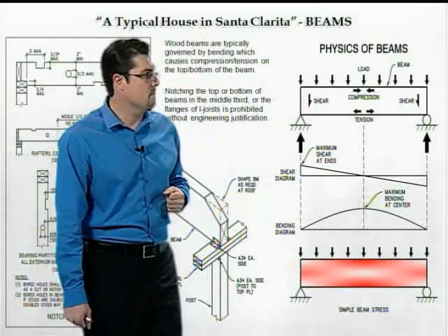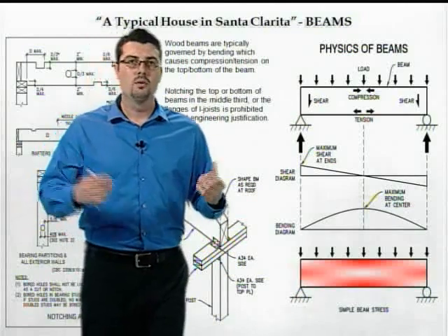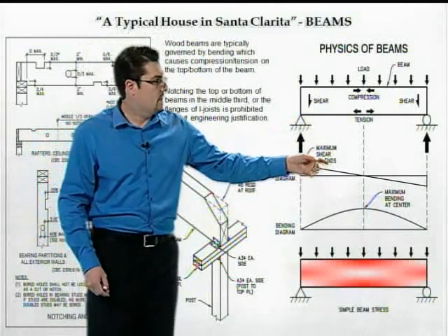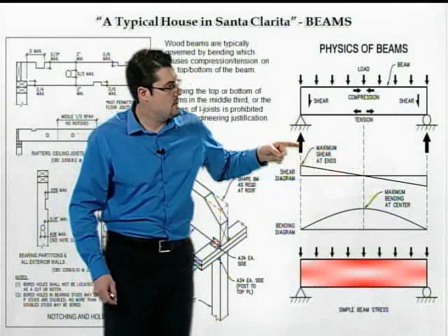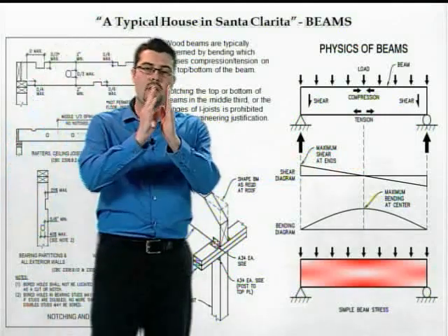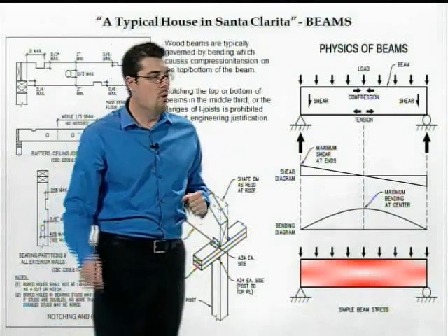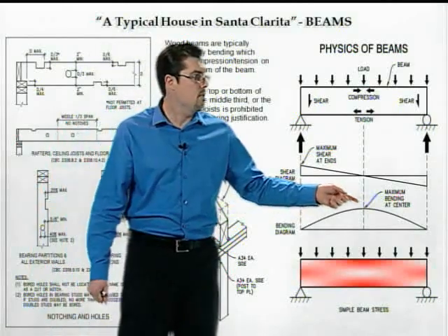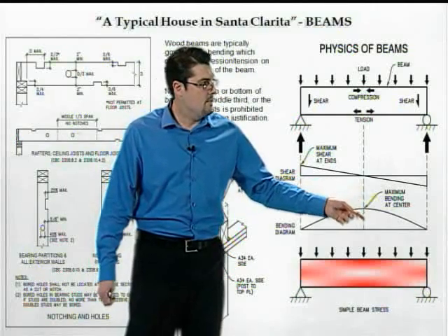Now, typically in a beam, when you load a beam from the top, it generates forces inside the beam. We call these forces shear and bending. As the load bears on the beam, the shear forces will build from the center of the beam and increase toward the reaction. Those are vertical forces that literally shear the fabric of the beam. More importantly, what usually governs the design of beams is what we call bending forces, or sometimes you'll hear the term bending moment. And bending forces are the largest at the middle of a beam.